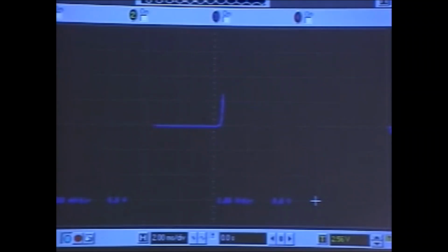Let's switch to the next one, called a diode. A diode looks like this. If the voltage across the diode becomes positive, around 0.6 volts or thereabouts, current begins to shoot up. But if the voltage is below that threshold of 0.6, then my current is almost 0. It's another lumped element called a diode, and you will begin using these elements in your 002 lives to build interesting systems.